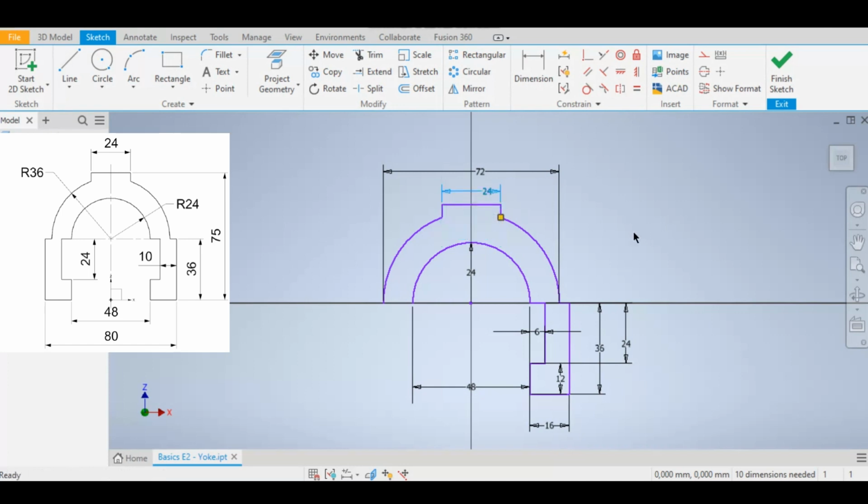There we go. So here you can see we've got our right hand side of our drawing almost complete, and we've got all of these dimensions. If you want to change a dimension, let's say we want to change the base footprint here. I'm going to double click on this dimension and this pop-up will appear. You can see the calculation that was done.